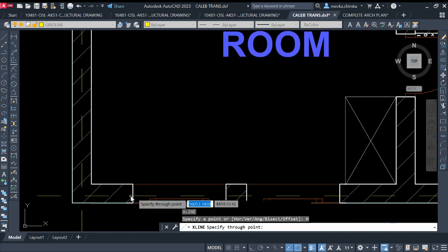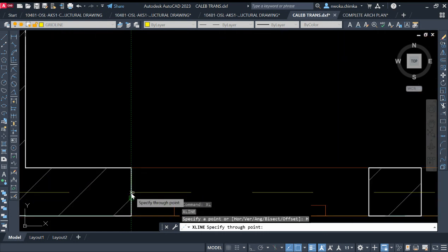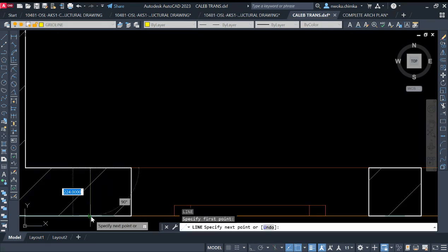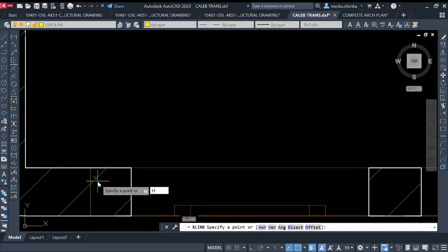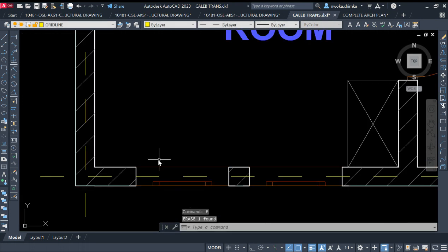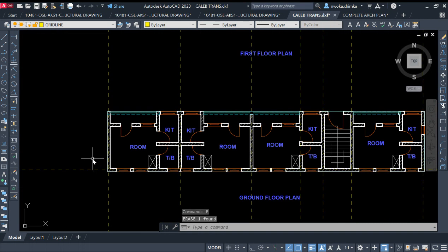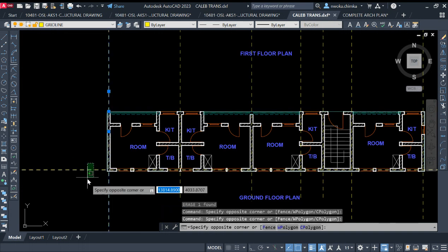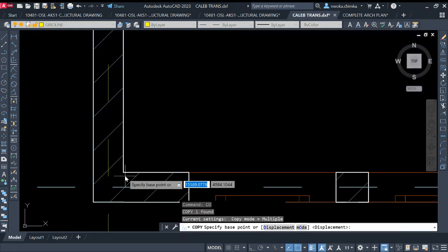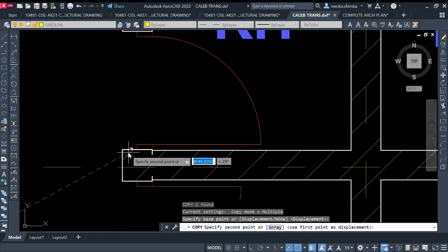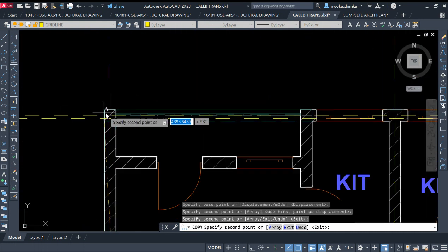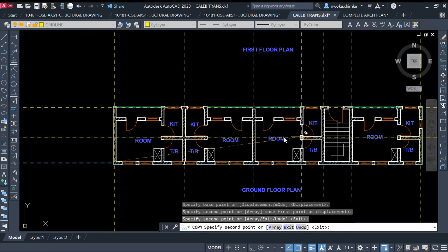And I'll locate the center of this wall, and you can see that we can find the center here. So I have to create a line first to show my center here. I'll now do XL, enter, horizontal, enter, which is H, and then find center and put it here, and then delete this immediately. So you can see that we now have a vertical grid line and also a horizontal grid line. So I'll copy the horizontal one and begin to place it at all the horizontal walls. I'll copy this and come here and place this here, and come here again and place this here also.